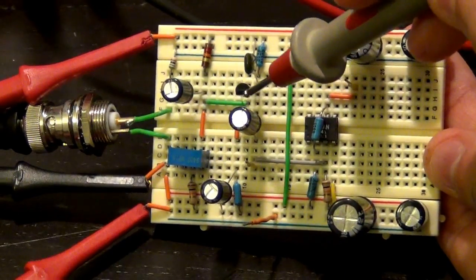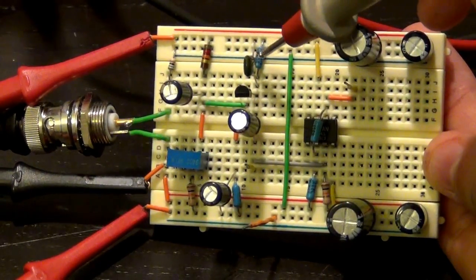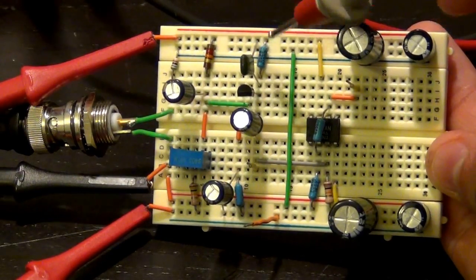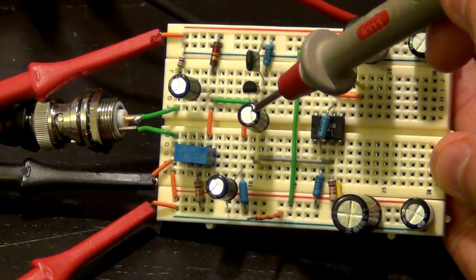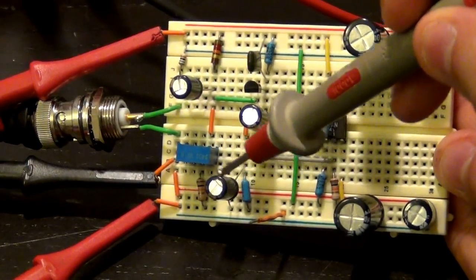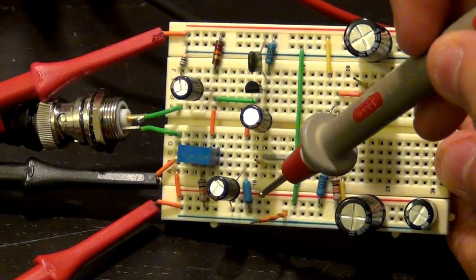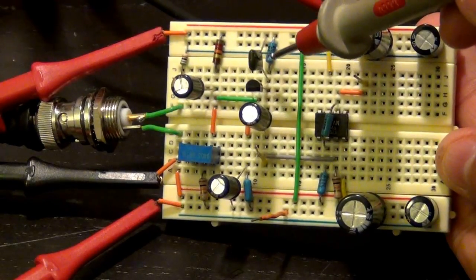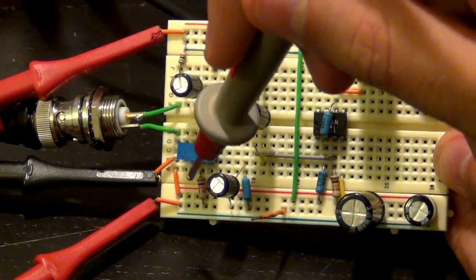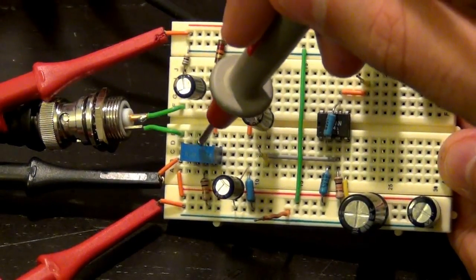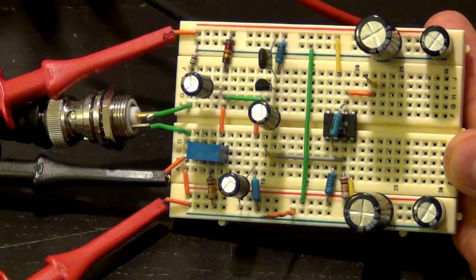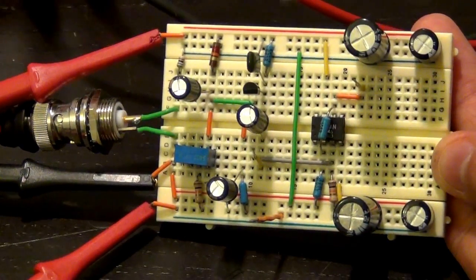Here's our bipolar device right here. Here's our collector resistor and the capacitor that limits the bandwidth to 20 kilohertz. This is the series capacitance to the next stage. We'll talk about it after. And here's our shunt capacitor across the emitter resistor. So the emitter resistor, the collector resistor, the transistor, and the bias resistors are here and here. I'm using a little potentiometer here because I didn't have exactly the value of the resistance that I wanted, so I'm just adjusting it based on what I need.